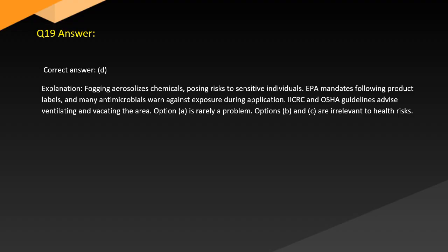Correct answer: D. Explanation: Fogging aerosolizes chemicals, posing risks to sensitive individuals. EPA mandates following product labels, and many antimicrobials warn against exposure during application. HVACR and OSHA guidelines advise ventilating and vacating the area. Option A is rarely a problem. Options B and C are irrelevant to health risks.